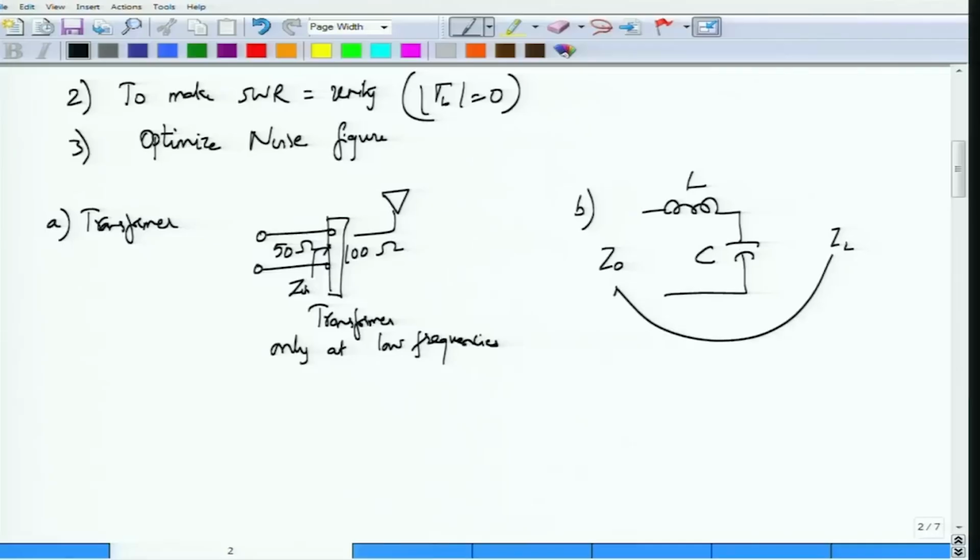So it can actually transform, if you were to put this lumped element matching network, as we would call. So why do we call this lumped element? Because for frequencies up to say 1 gigahertz or slightly higher than that, the values that you obtain for the inductor and capacitor can actually be realized, even on a printed circuit board, using lumped elements. You can actually buy these inductors or capacitors and then place them at appropriate points on your matching network. Now that is obviously not going to work if your frequency goes beyond say 1 gigahertz. 1 gigahertz is already stretching it too much.